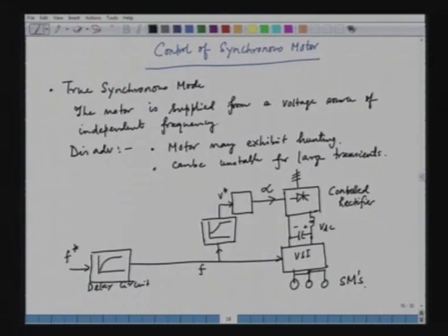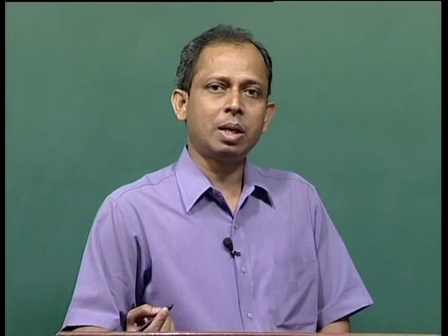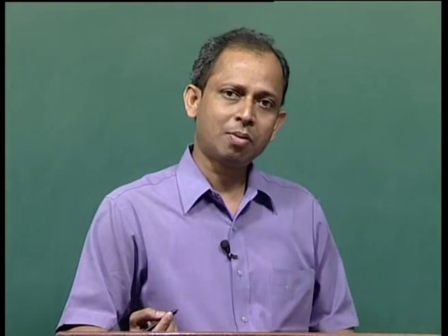So, this frequency change here F is not very abrupt, because of the delay circuit the frequency change is gradual, but this cannot be used for very high performance drive system, because we cannot change the speed immediately. So, we have to have a mechanism of changing the speed starting from 0 to the full speed with good dynamic response. So, we go for what is called a self controlled mode. So, we will see actually what is a self controlled mode.